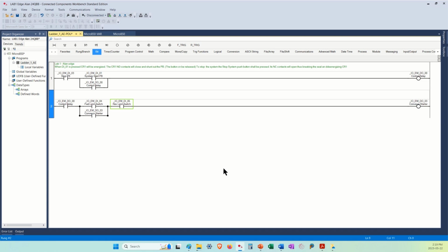So amend this program so now you have 3 normally open input instructions that are ANDed, and 2 of them are ORed or latched. Include all comments and instruction on the run. So now we have to type in here a description of what the run does.